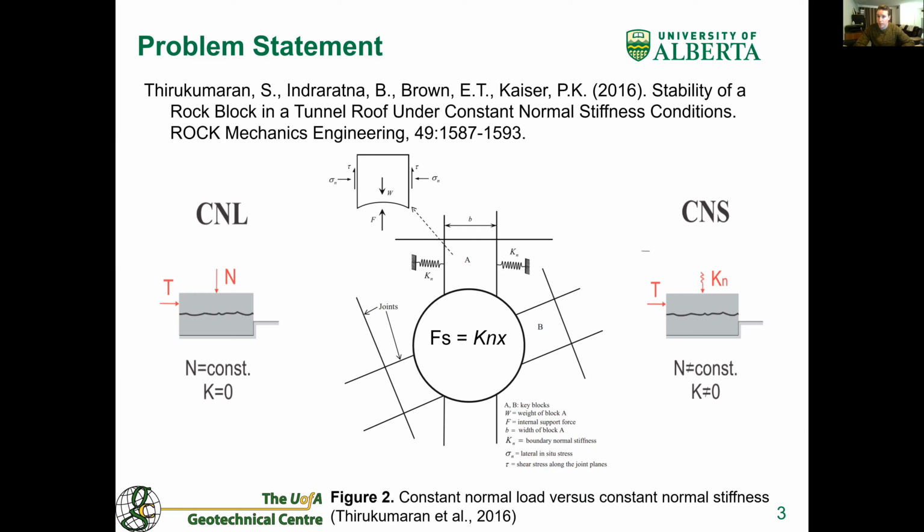The second shortcoming of traditional triaxial tests is that they only capture external pore pressure measurements. The extremely low permeability of overconsolidated clays and clay shales mean that these external measurements are likely not capturing the true internal pore pressure response of the material along the shear band.